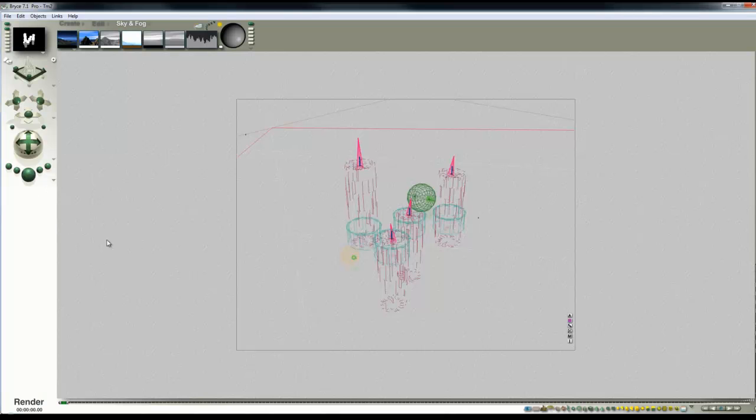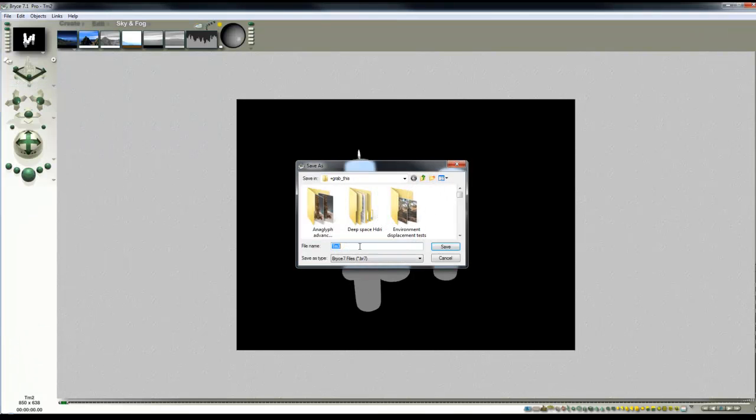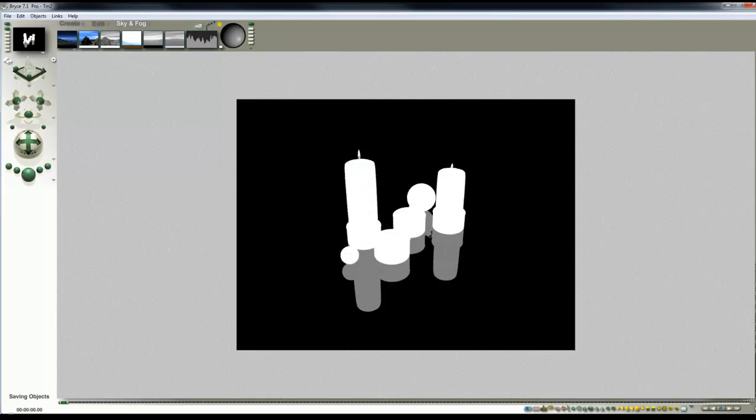Also get rid of that for a second. I don't need diffusion for now. I'm just thinking about the shadows. So, in order to generate the shadows, I'll use a negative light, and use a negative light where the light source is. So if I save this at the moment, save as tm2 mask, I'll show you a trick to get something in from another file, which I inadvertently deleted.